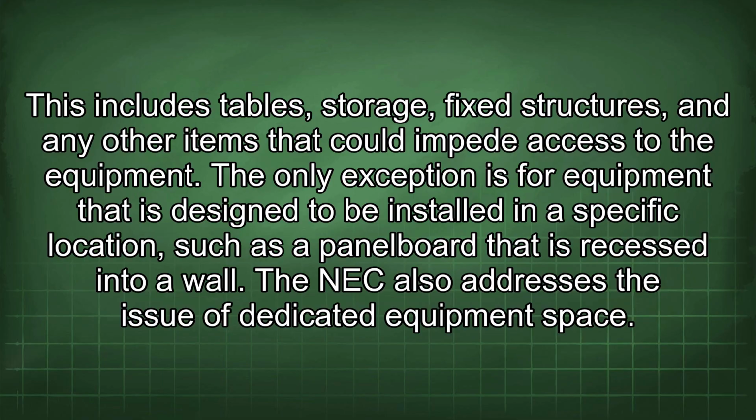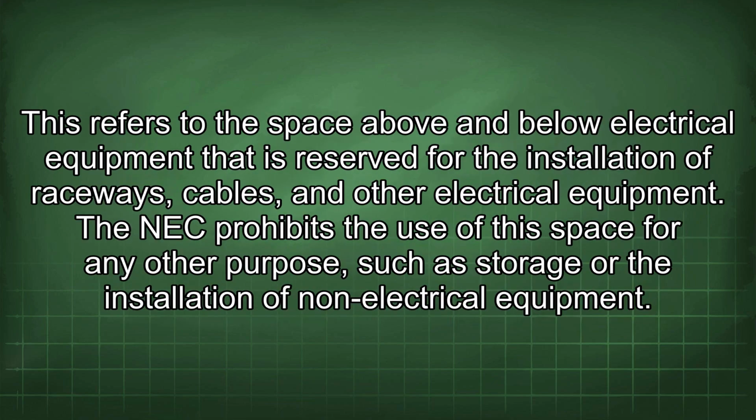The NEC also addresses the issue of dedicated equipment space. This refers to the space above and below electrical equipment that is reserved for the installation of raceways, cables, and other electrical equipment. The NEC prohibits the use of this space for any other purpose, such as storage or the